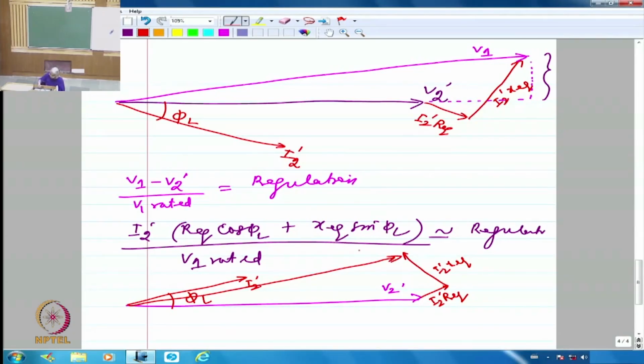This is going to be my final value of V1. And you can see that V1 and V2 dash are almost of comparable length. In fact, if you had X more inwards, then your V1 would in all probability have been smaller than even V2 dash, which means the applied voltage happens to be slightly less as compared to what you get on the secondary side.